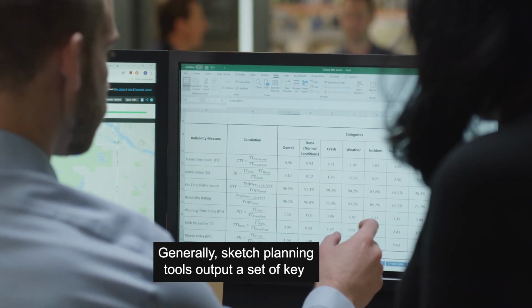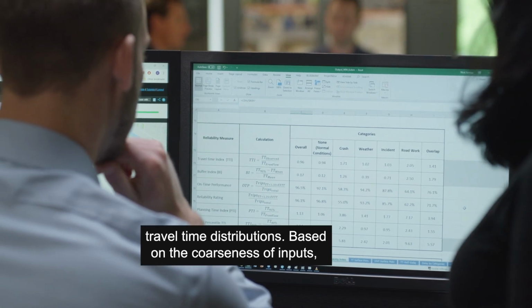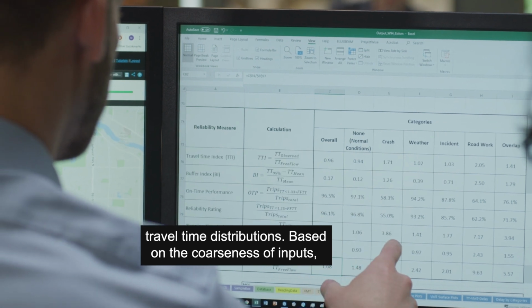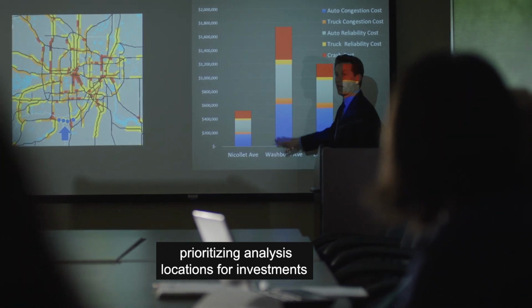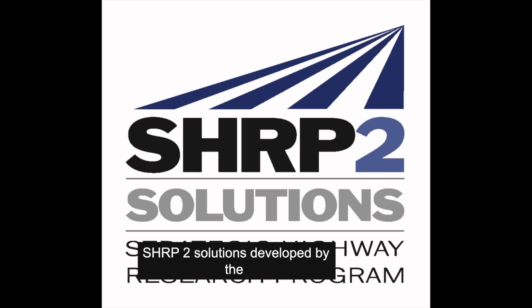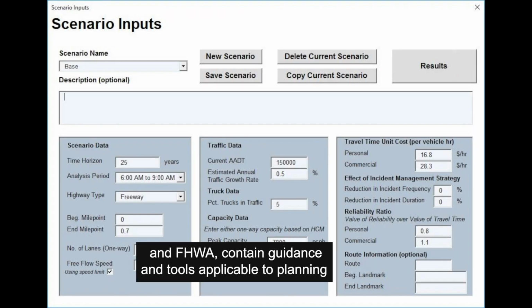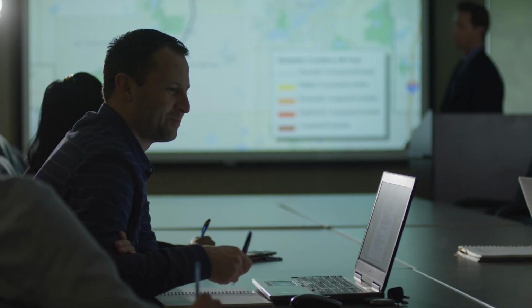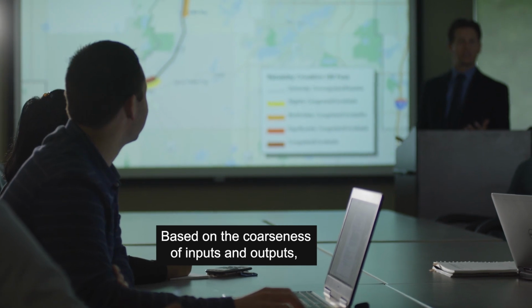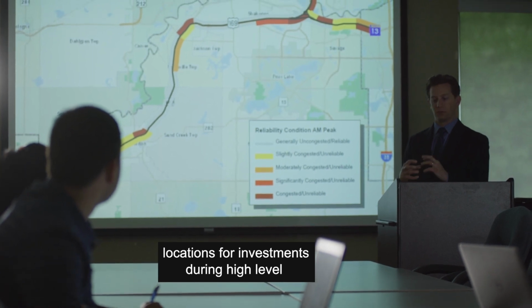Generally, sketch planning tools output a set of key reliability measures that can be used to estimate wider travel time distributions. Based on the coarseness of inputs and outputs, appropriate applications may include prioritizing analysis locations for investments during high-level planning efforts. SHARP2 solutions, developed by the Transportation Research Board in partnership with AASHTO and FHWA, contain guidance and tools applicable to planning-level reliability analyses, such as Project C11.